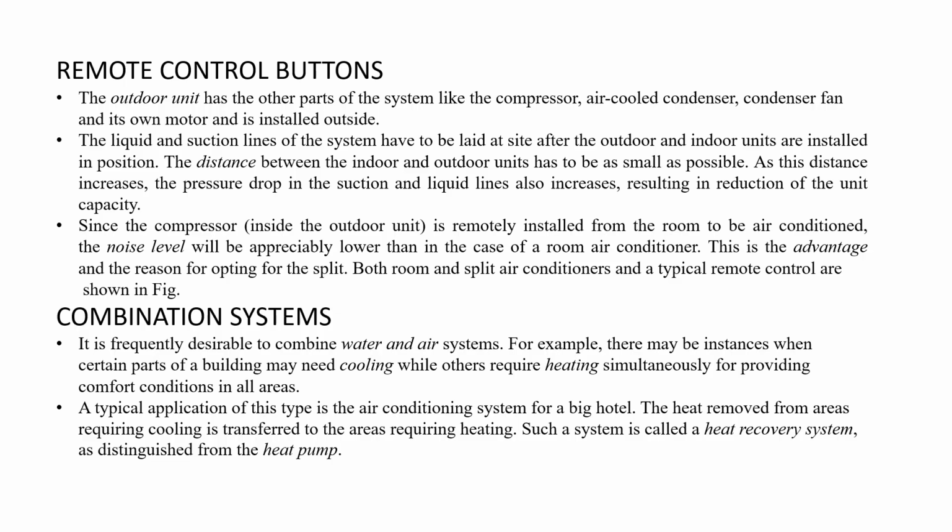Since the compressor, which lies outside, is remotely installed from the room air conditioner, the noise level can be made appreciably less compared to a room air conditioner. This is the advantage and the reason for opting for split ACs. Both the room and the split air conditioners and the typical remote control are shown in the next slide, where we will show how it works. I mean the remote control buttons are there, right?